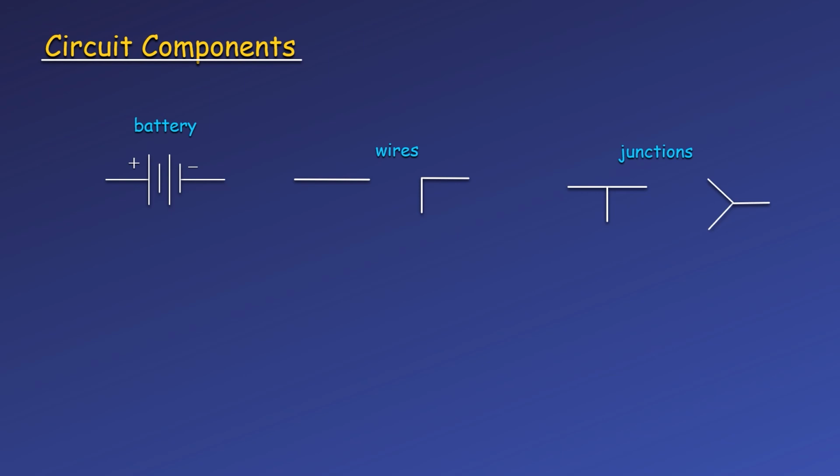Even if a wire splits or 2 wires come together and become one, because they are all ideal, they will still all be at the same potential. However, the current or charge flowing through the wires may be different. If a wire splits, some of the current will go through one branch and the rest through the other branch. If 2 wires are bringing current together, it will all leave in the wire where they meet. Because of this difference in current, we will differentiate between the wires coming into or leaving a junction.